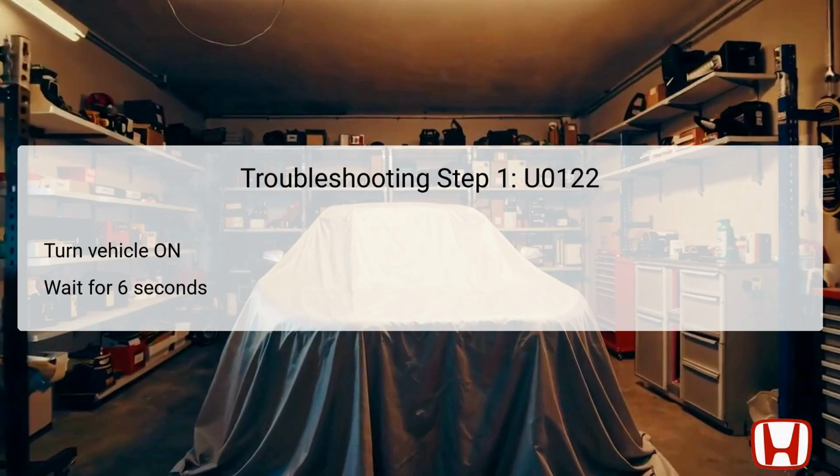After this wait period, it is essential to monitor the dashboard for any warning indicators that may appear due to the initialization of the VSA modulator-control unit. This method helps to establish a baseline for further diagnostic efforts. If the code persists after this step, it signifies the need for deeper analysis into the power, ground circuits, or the components involved in the communication pathways.